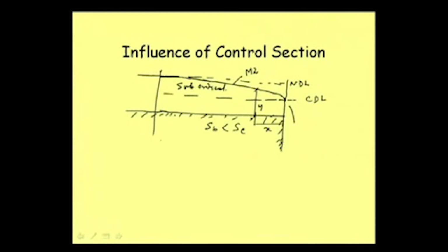Well, one thing we can do is start from uniform flow and then start computing in this direction. We will compute till the flow is just higher than critical depth, because at critical depth this cannot be computed, because our slope becomes infinite and that is not computable. So just above the critical depth we can compute and we can stop. That way we will get the total length.